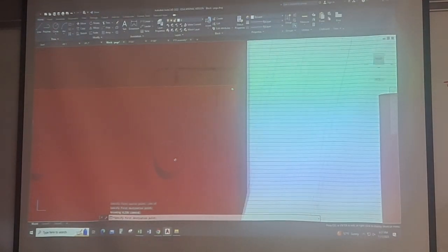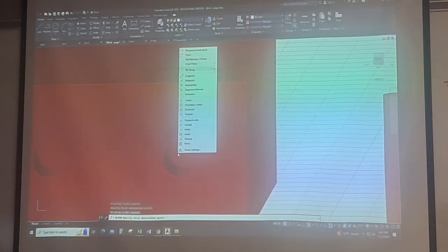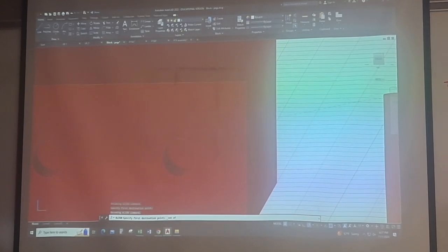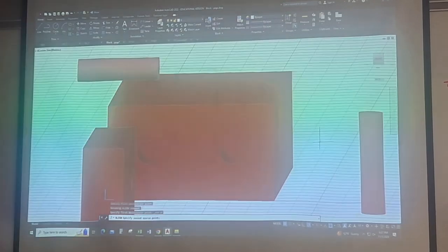So what I'm gonna do is roll that up a little bit, and then I'm gonna force that object snap point on AutoCAD. I'm gonna tell AutoCAD center, and that way I can just come in here and get around the curl of that back right. I cut that little slot, that little peg hole out. I can get back up inside there by rolling this around to where I can see, zooming in a little bit, and then forcing that object snap point to guarantee that I get the correct point out there. So I select that source and destination.